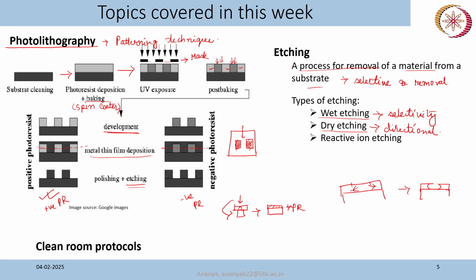See, here in this figure, let's first consider positive photoresist. These portions are exposed with UV light. Then what you do is dip it inside a developer solution. You will dip your substrate and the exposed photoresist inside this developer solution. Now the portions that were exposed to light become soluble, so these portions get dissolved in the developer solution, and after that you get these patterns.